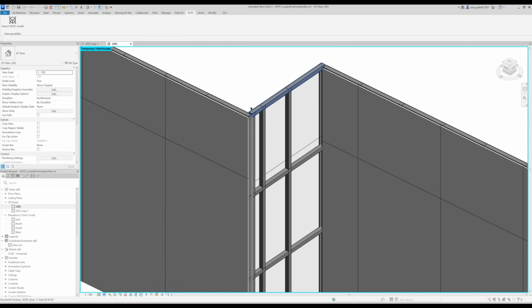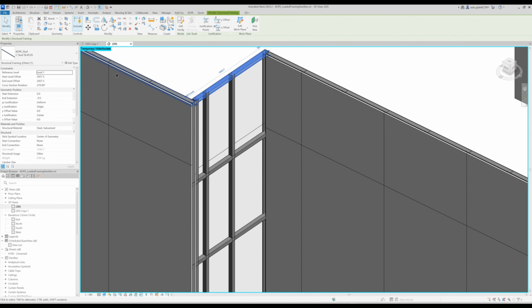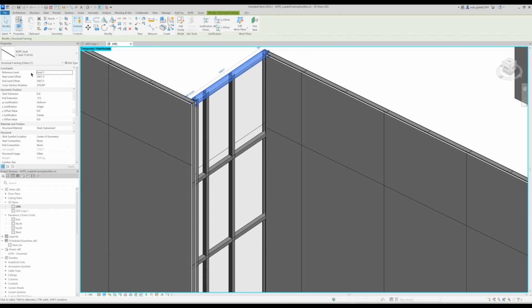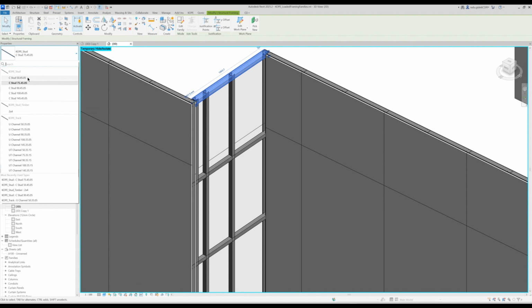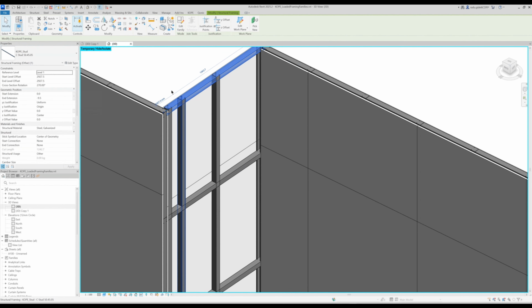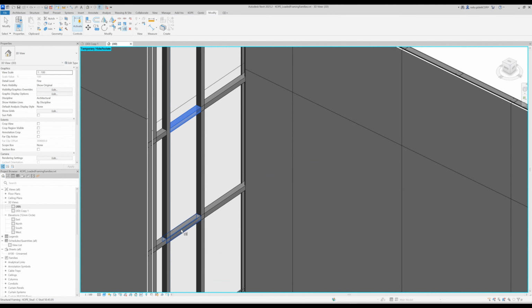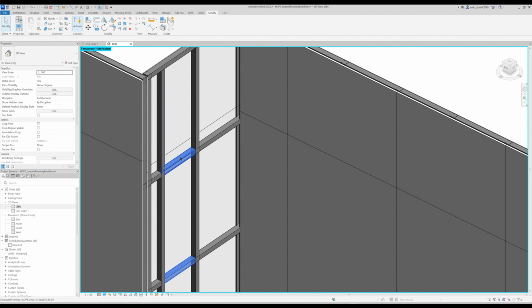So that's the beauty of going down this path rather than some custom geometry and requiring you to use specific plug-in tools inside the plugin to even move things or things like that. So we're able to change a framing member. We're able to, I don't know, trim a few of these structural framing beams. We can actually put a hole into the boarding by placing a family.